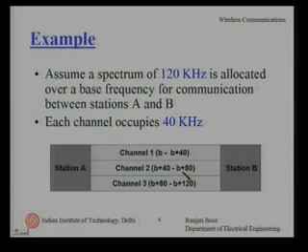Clearly this is idealized, because we do not have the luxury to so neatly partition the bandwidth. What determines that we can have sharp cutoffs? Well, there will be a receiver with a filter, and the filter characteristics will be in part determining what kind of channel bandwidths are being actually used. So there is a difference between what you allocate and what you end up using. So what will happen in a real life scenario